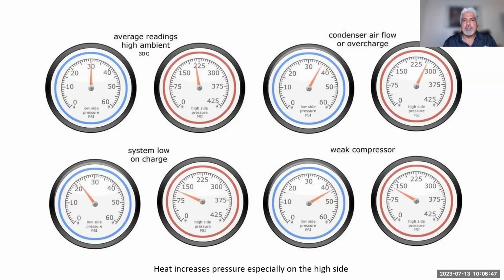Now, if they're both about the same and the compressor's engaged, I believe we had a question last week about that. That could be a stuck open thermostatic expansion valve, but it could also be, again, the reed valves in the compressor or one of the pistons in the compressor might be going out. So therefore, we're not pressurizing enough, or we're not, again, generating enough suction.